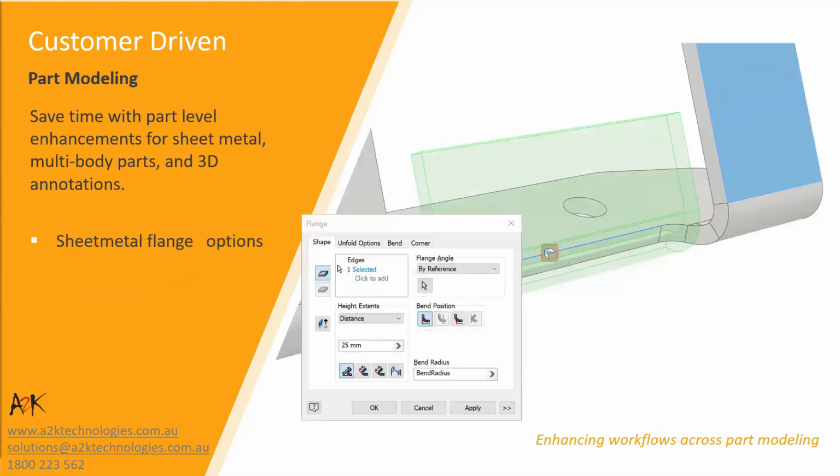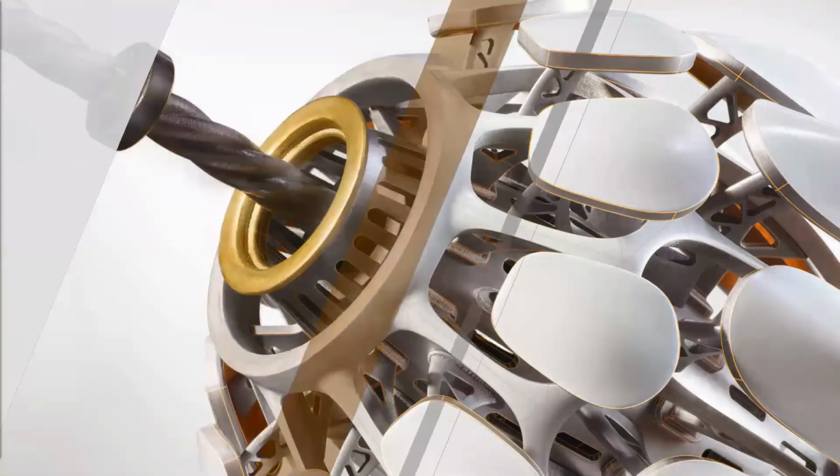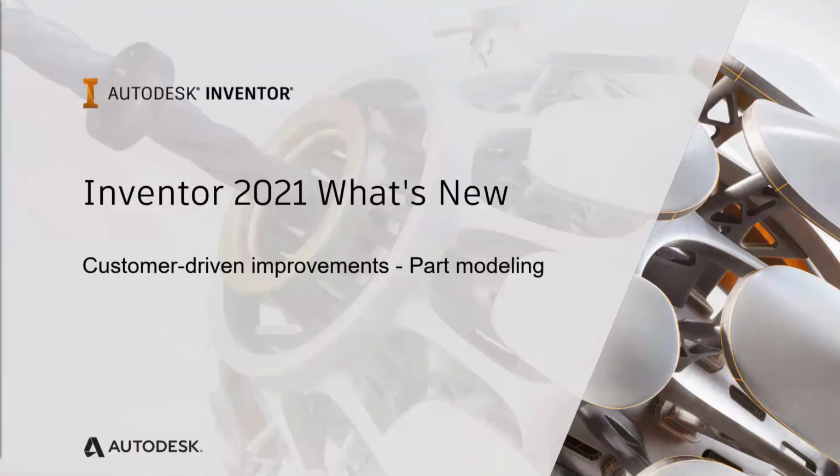So that set flange angle by reference. New options have been added that let you specify the flange angle by value or by reference. Use the by reference option to select a planar face, planar surface, origin plane, or work plane to set that flange angle.